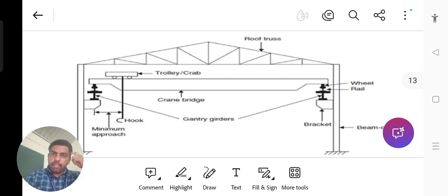This is the main difference between the plate girders and the gantry girders. It should carry moving loads. When the vehicle passes in that situation, there will be an up and down jumping motion. In that situation, the total load should be carried and distributed equally.